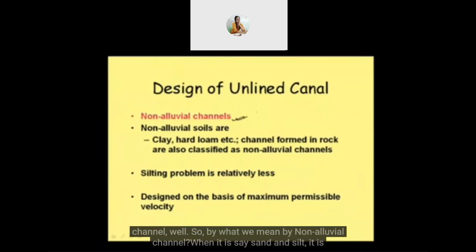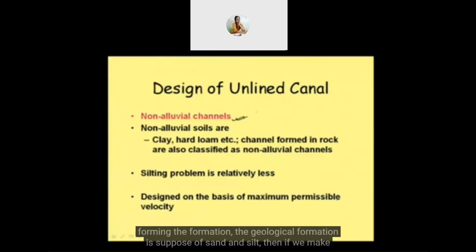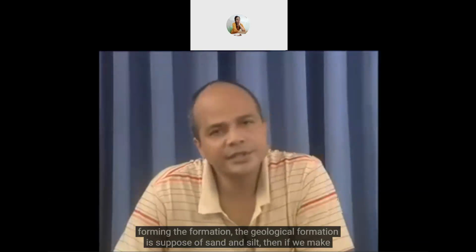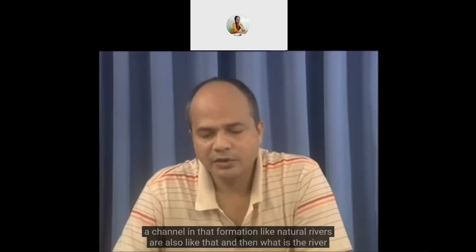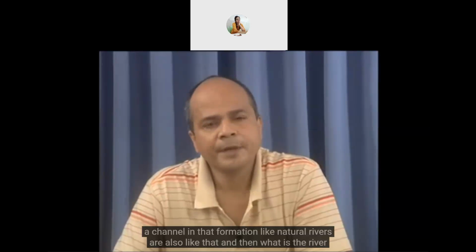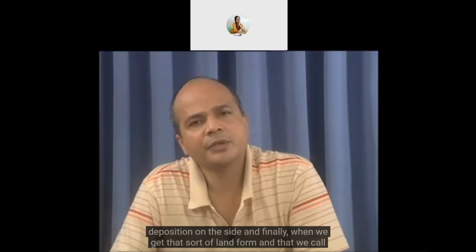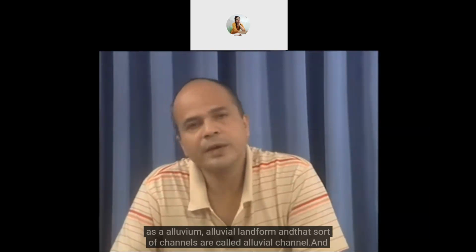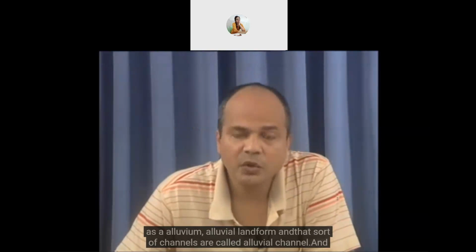Well, what do we mean by non-alluvial channel? When the geological formation is composed of sand and silt, then if we make a channel in that formation, like natural rivers are also like that, the river deposits on the side, and finally when we get that sort of landform, we call it an alluvial landform, and that sort of channel is called an alluvial channel.